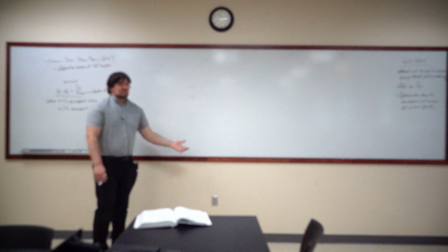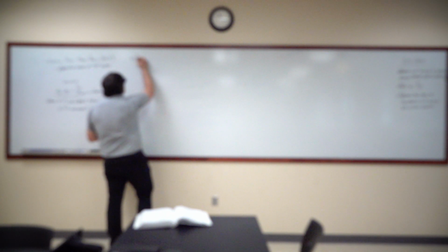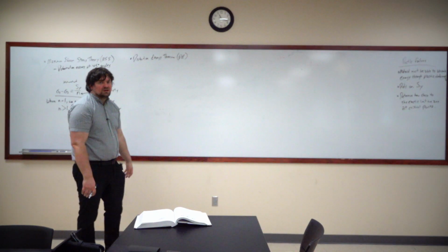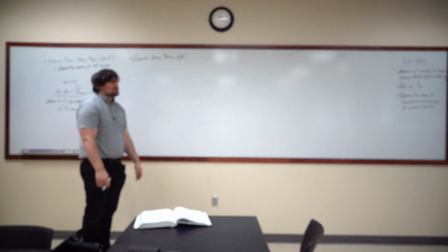Okay? If we want a more accurate stress valuation, something that fits better in some steels and a lot of aluminums, we're looking at a different stress theory, and this is where we introduce distortion energy theorem. This is also called DE, okay? Now again, this very much has to do with the intermolecular bonds and the energy that's stored within those intermolecular bonds. Derivations are in the textbook, I am not going to cover the derivation again, even though I think the derivation has value. Using the equation is more important to me.